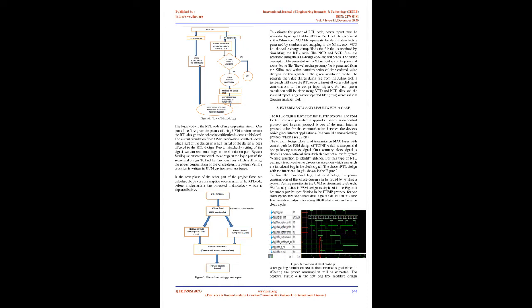The value change dump file is generated from the Xilinx tool, which contains a series of time-ordered value changes for the signals in the given simulation model. To generate the value change dump file from the Xilinx tool, a test bench will drive the RTL code to insert all other valid input combinations to the design input signals. At last, power calculation will be done using the VCD and NCD files, and the resulting report is generated as a .pwr file, which is from the Power Analyzer tool.